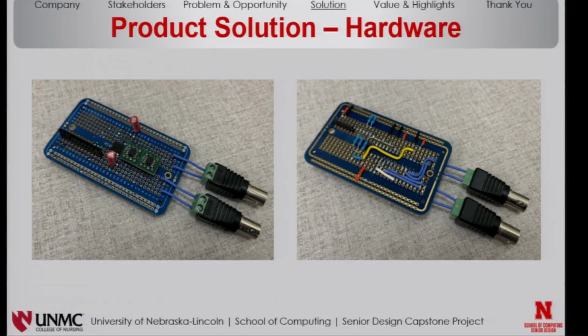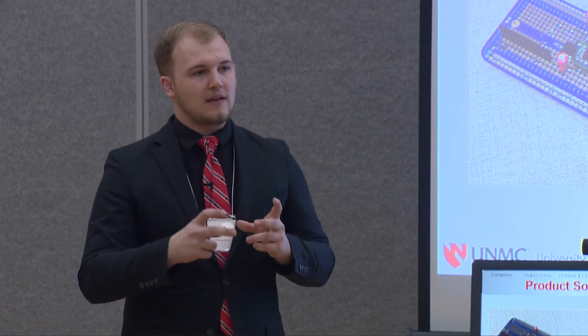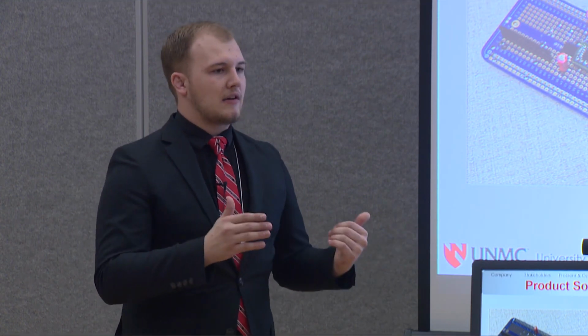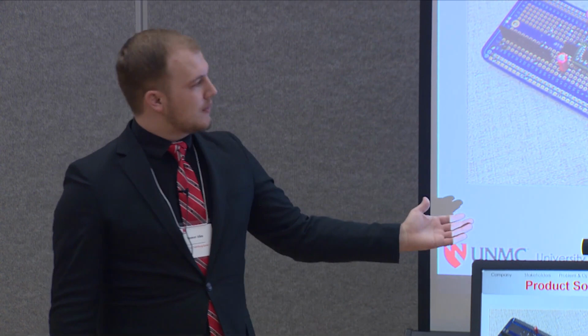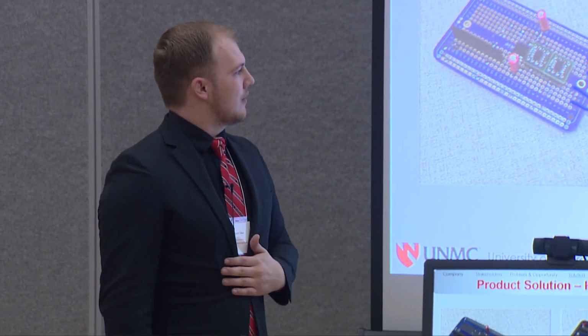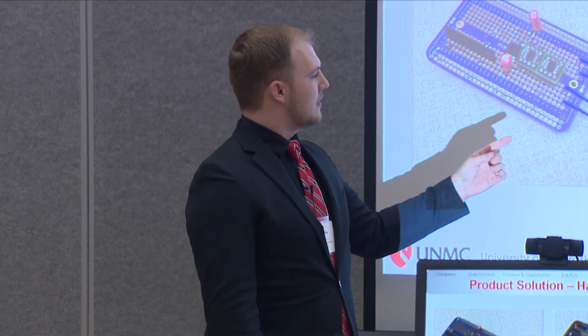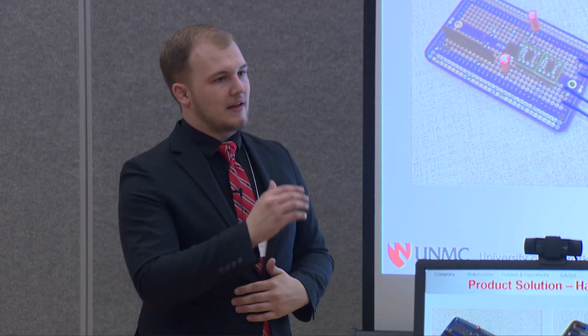Right here is the actual analog circuitry for this. We wanted to be able to take in 5 volts for the ADC, so we can measure 0 or plus to minus 5, and the board itself that we were using could only accurately do it from plus to minus 1 volt, so we had to leverage some circuitry, some op amps, a bunch of just electrical engineering stuff to get it to send a signal that we're able to read with FPGA on the board and then transfer all the way through.